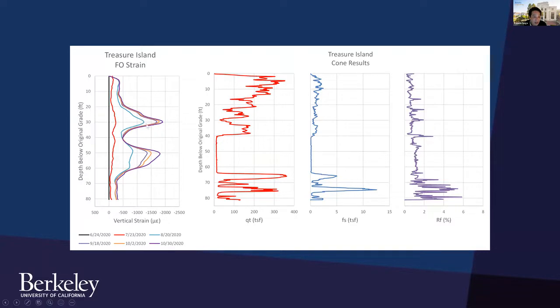But there's another one over here, giving a large strain development, implying there's a soft part locally, and that corresponds to this particular point. So it starts to give you interesting information about which parts are mechanically behaving how, this is cone resistance, but how they link to the actual behavior of the embankment settlement.